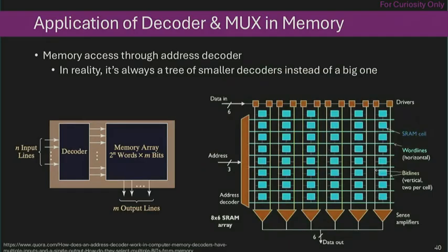All right. Just going to show you one realistic example before we conclude the lecture. Decoders and multiplexers are used very commonly in memory construction. Memory has a bunch of these blue cells. Each of them you can think of as 1 bit of the data. And you have multiple lines. Think of every line as 1 word, a multi-bit group of data. To write something to the memory, or read something from the memory, you want to enable one of these lines.